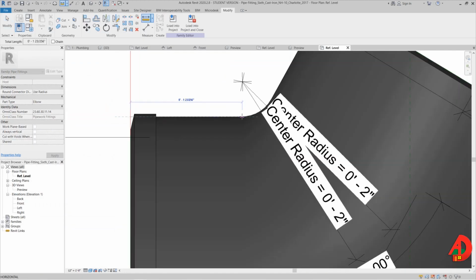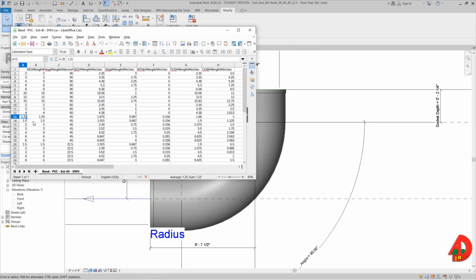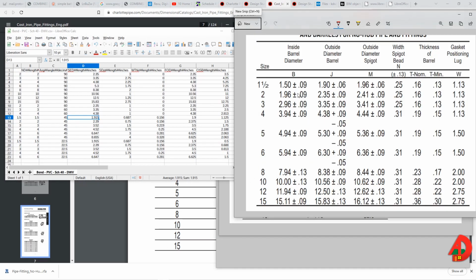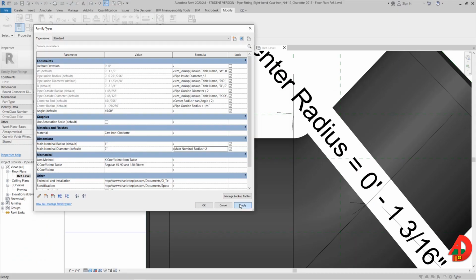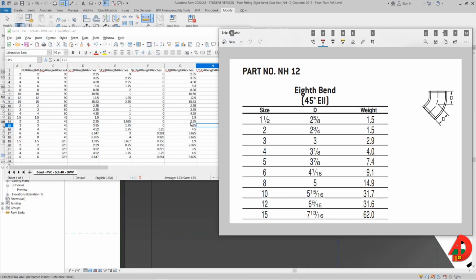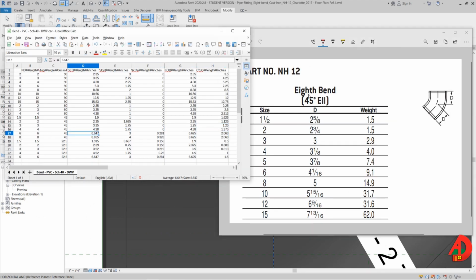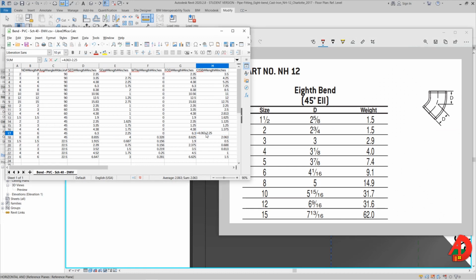Now I am going to repeat the same procedures for the other dimensions and angles, and I will fast forward for that. In summary, all I do is to find the right dimensions using the manufacturer website Revit family and the dimension catalog and insert them in the right place in the lookup table. If I need to, I can also delete or add rows to make sure I have only the sizes in the catalog.